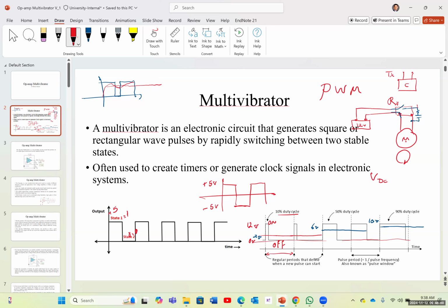The reason is this. Sometimes in a circuit, for example when water gets inside and the PCB board is wet, the circuit will be short-circuited or grounded, and it will show us 0 volts in the output. Now the system doesn't know: is this 0 volts a logic of zero, or is it an error in the system?